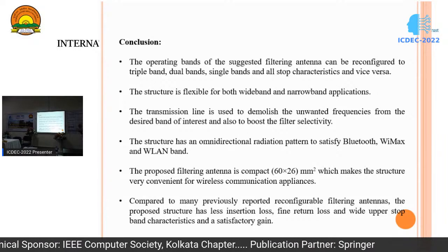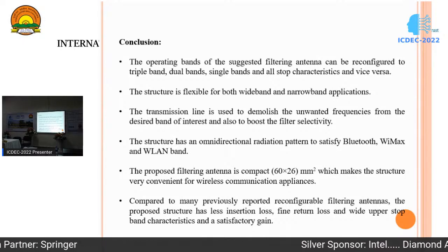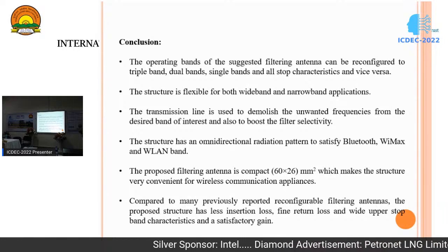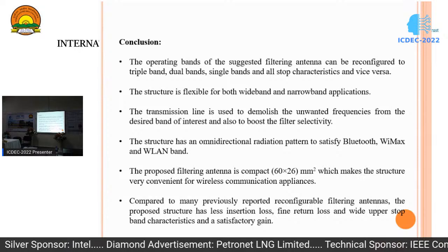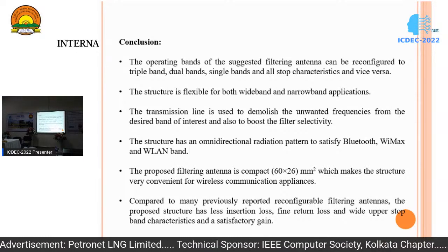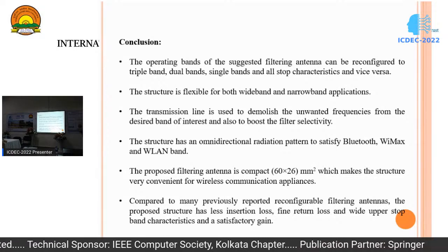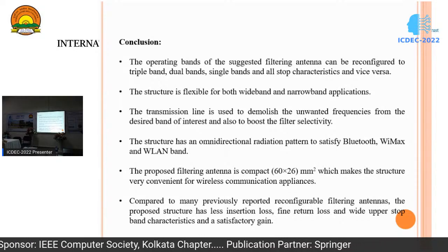As it is providing the omnidirectional radiation characteristic, it is satisfying the WiMAX and WLAN bands. And if you see the size, the structure is very compact, 16 by 26 millimeters square. If we compare the performance parameters with previously reported structures, the proposed structure has less insertion loss, very high return loss, and also provides satisfactory performance.